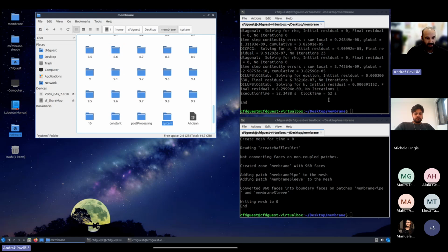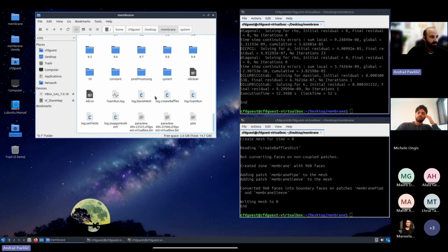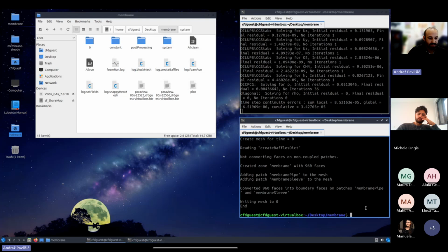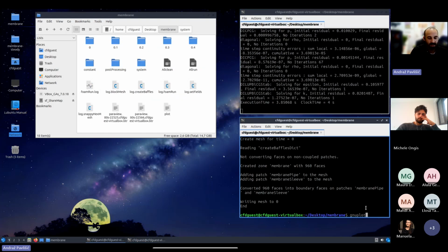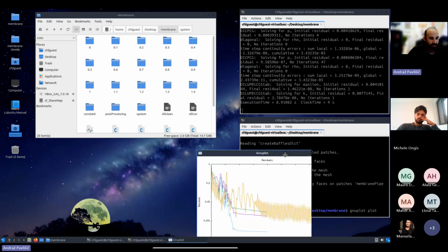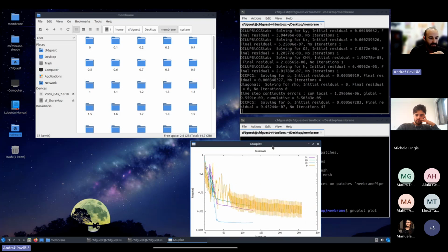So now the question was why have two different terminals? While we are running the calculation, I said that we can follow our residuals. So for now, I'm going to again erase all the calculation I have done, and rerun our calculation from time 0. Because while doing that, I can use a different program called gnuplot, which is almost always part of the Linux system.